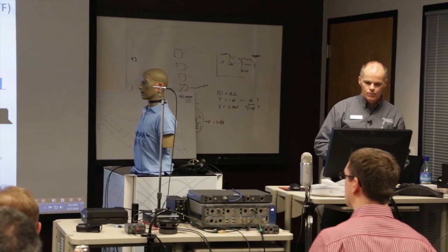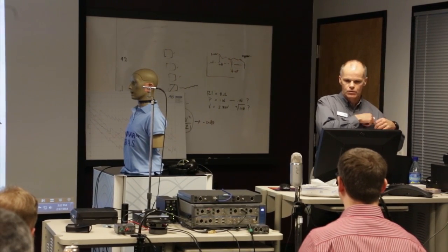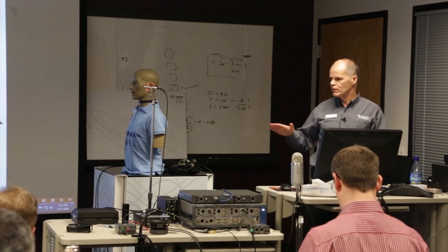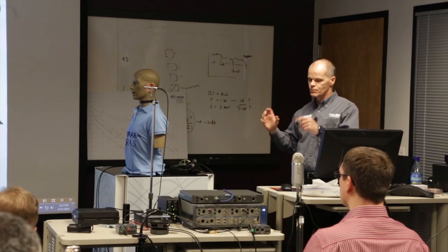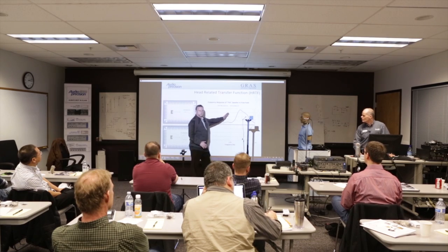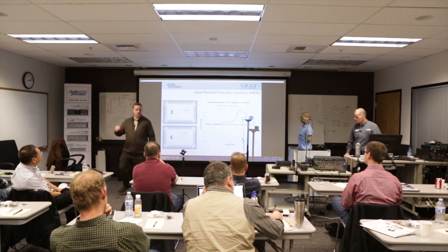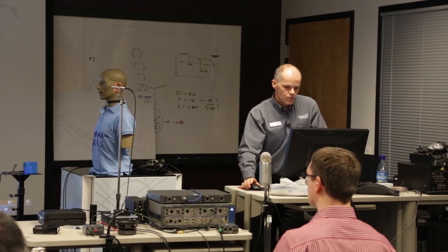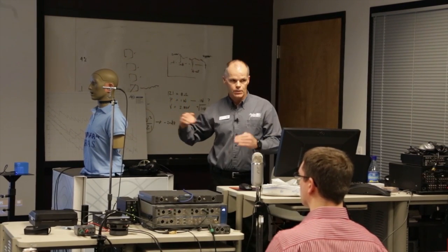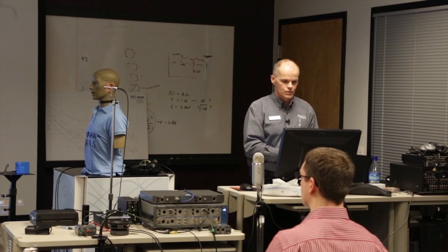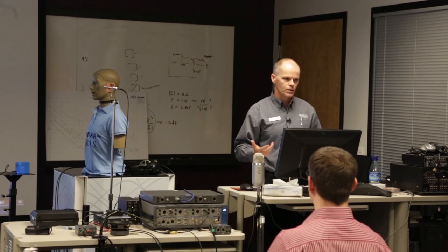So to do this measurement properly, this would be done in an anechoic chamber. And as Bob mentioned, you get a different head-related transfer function for each angle of incidence. So not only in a horizontal plane, but in three-dimensional space. It fundamentally just shifts this just a little bit one way or the other, depending on which angle we're at. But it's the same curve. So you can actually translate a measurement from inside the ear simulator into the free field. And essentially you would take that inverted curve and subtract the levels in dB or divide them in linear units.